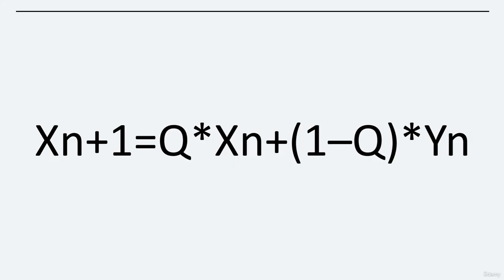The Wegstein equation is used to determine the value passed to the outlet stream for each accelerated iteration. X is the value of the outlet stream assumed. Y is the value in the inlet stream calculated. N is the iteration number. And Q is the acceleration factor.